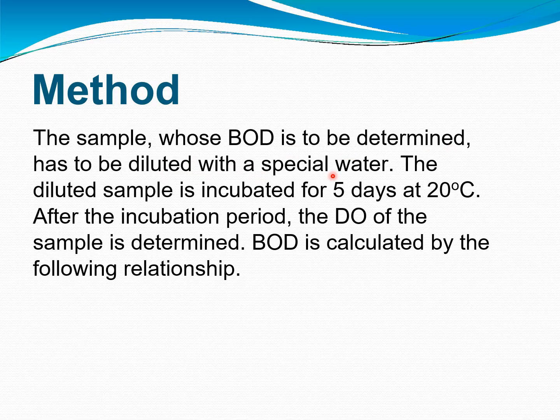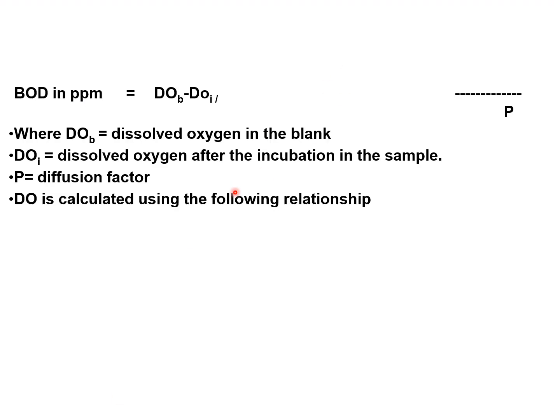a special water. It is nothing but distilled water only. The diluted sample is incubated for 5 days at 20 degrees centigrade. This temperature has to be maintained for 5 days continuously. After the incubation period, the dissolved oxygen of the sample is determined. BOD can be calculated by using the relationship.